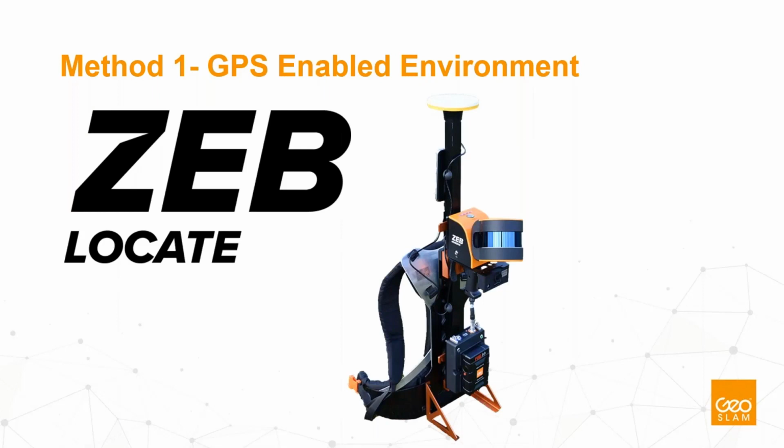The first method, in a GPS-enabled environment, an open pit mine, let's say, or somewhere where your stockpiles are, we can use the ZEB Locate, which utilizes the ZEB Horizon, as you can see. That's the handheld scanner that we simply just slot on the back of this backpack unit. And then on top of that backpack unit, we have our GPS receiver. We can just simply walk around an area then, and all the data we collect is georeferenced straight away using the GPS receiver. Nice, simple workflow.